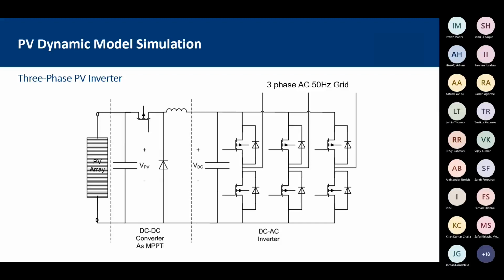That's very simple. But when it goes into a power system, like a dynamic, grid-connected PV system, there are a lot of other controls we need to have in our PV system, because we need to meet certain requirements from the grid code. Those are called grid compliance requirements.